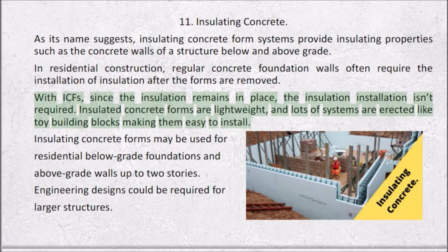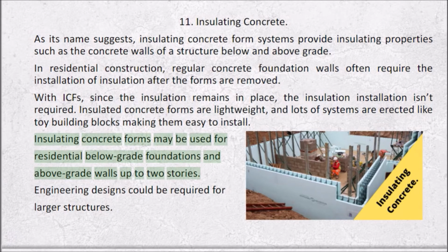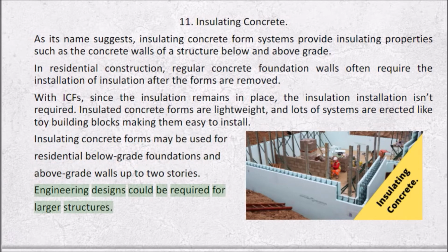Insulated concrete forms are lightweight, and lots of systems are erected like toy building blocks, making them easy to install. Insulating concrete forms may be used for residential below-grade foundations and above-grade walls up to 2 stories. Engineering designs could be required for larger structures.